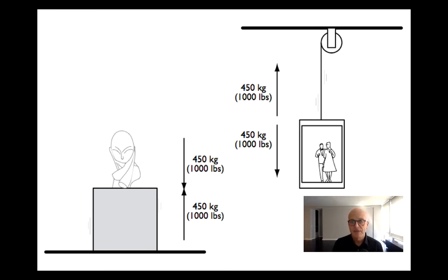So on the left, we have a sculpture that weighs 1,000 pounds, and we have a podium or a pedestal that is made of a material that's capable of building up enough internal stress to support that sculpture. And the way we draw this is with 2 opposing arrows. The gravity load of the statue is pulling down, toward the center of the earth, 1,000 pounds. And the capacity of the pedestal to hold it up is pushing up, right? It's a reaction. It's happening within the pedestal.